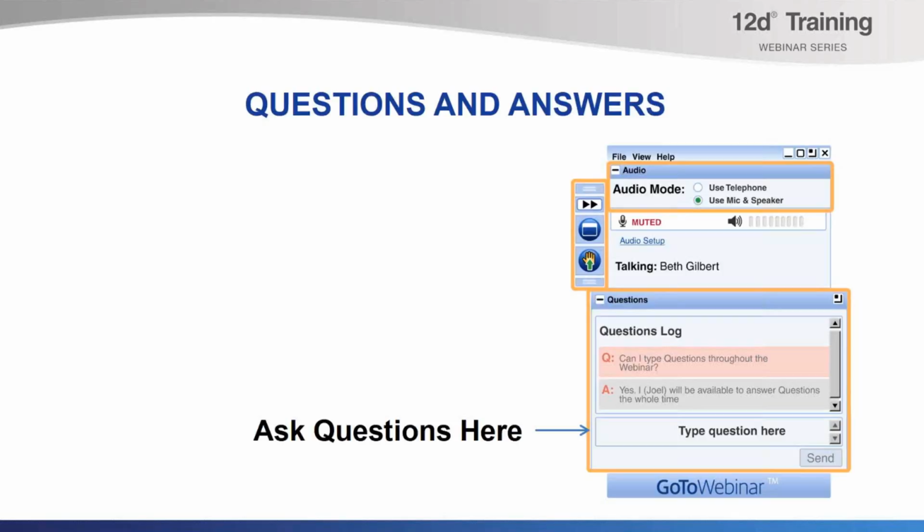I think we've just got time for a couple of questions. John in Perth has asked, can chainage equalities be used for roads as well as rail? Yeah, they certainly can. I've seen them used for road jobs where they want to round a chainage off so that they might have multiple contractors on one single job, and so they can round the chainage off to suit their contracts. Again, just be aware that you're not changing the real chainage of the string. You're just tricking the display into showing a secondary chainage on that string. So yes, it can be used for road work, as an example.